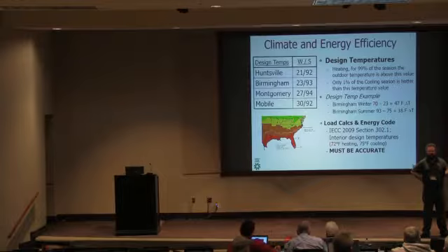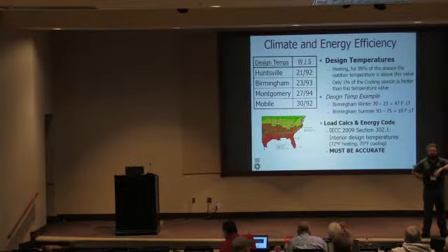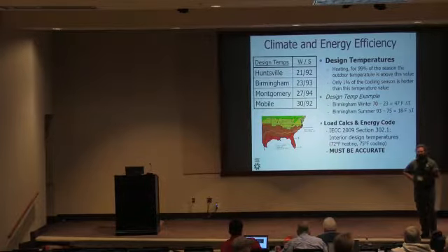Any new home, I would recommend a passive radon vent system that's pre-wired to become an active radon vent system, because it'll cost you a couple hundred dollars to put in at the time of construction, and it is basically protecting human health. And I think it's a good investment. And in an existing home, it can be retrofitted, but it's a trickier retrofit.